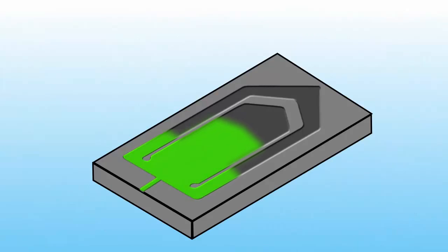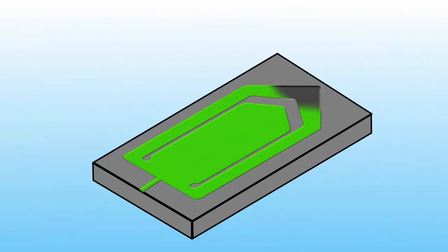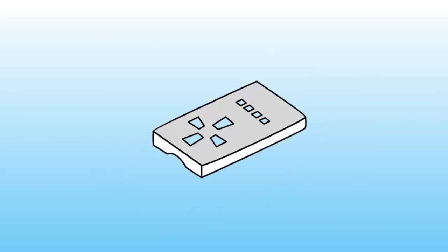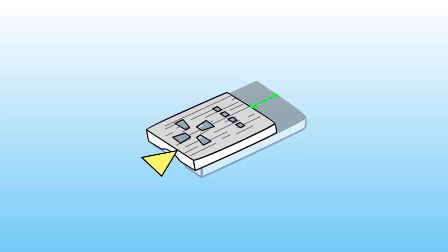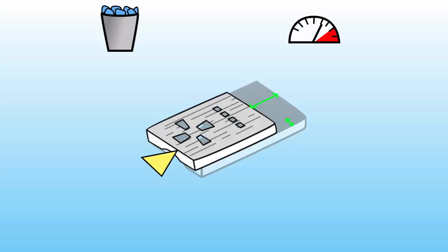When plastics are injected into a mold, they are subject to a new set of conditions that affect how they shrink. Plastic molecules tend to align themselves in the direction the polymer is flowing. This alignment, called orientation, influences how polymers shrink linearly. Many polymers shrink more in the direction of flow and less perpendicular to the flow. How much they shrink depends, in part, on the characteristics of the polymer, additives in the polymer, and the processing conditions used to make the part, including temperatures and pressures.